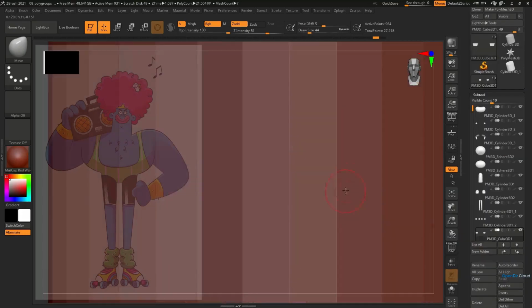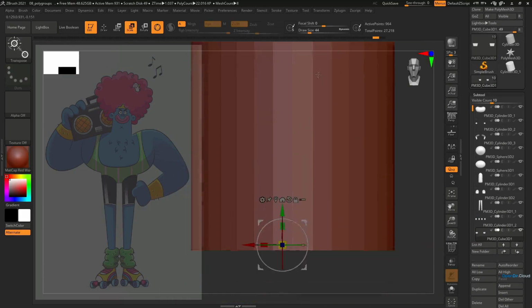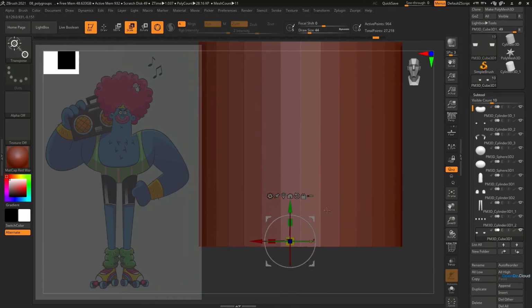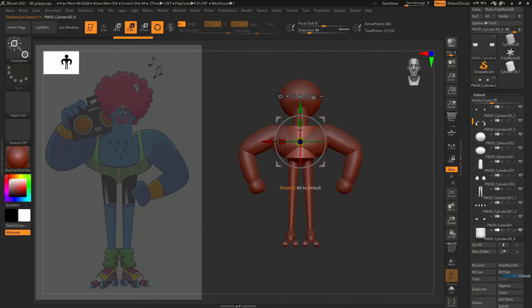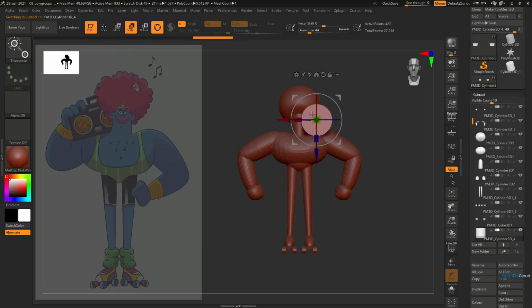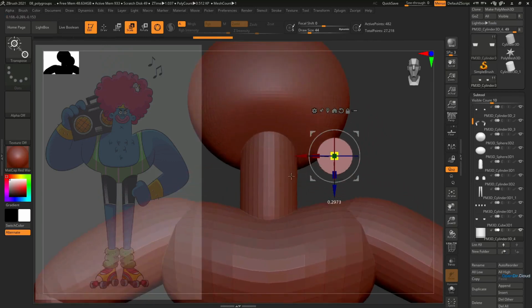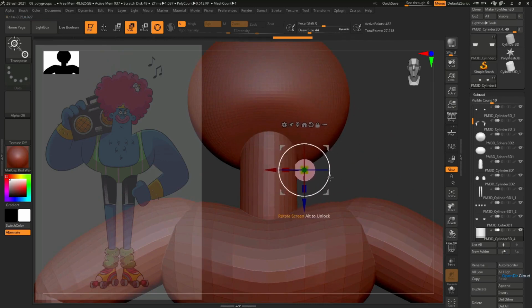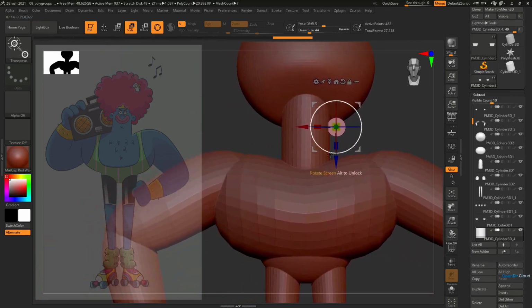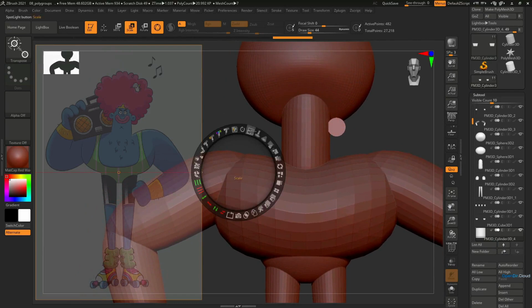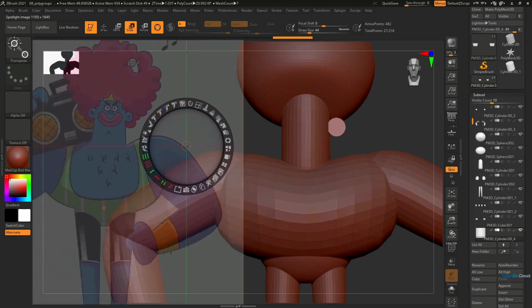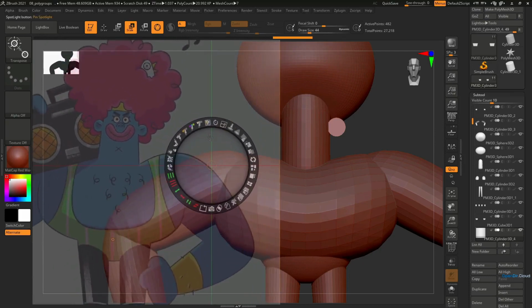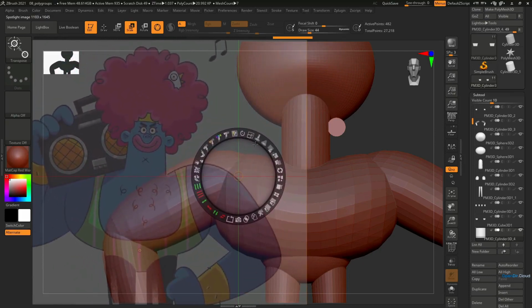The ears are also very influential on the silhouette. That's why let's add another cylinder. Highlight this subtool and make it an ear. Next, I want to edit the position of the reference in the spotlight. In order to do that, press the shortcut Z. Now you can scale the image and move it where you want. This way, it'll be much more convenient to adjust the ear. Press Z again to exit Spotlight editing mode.